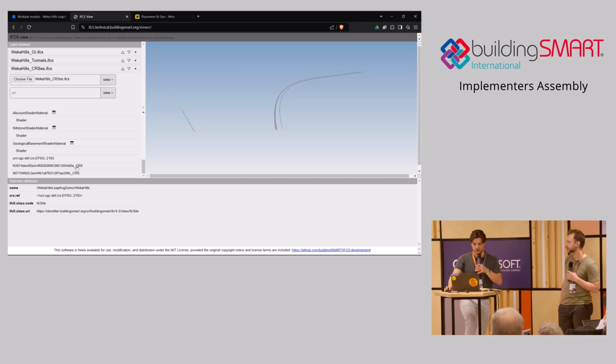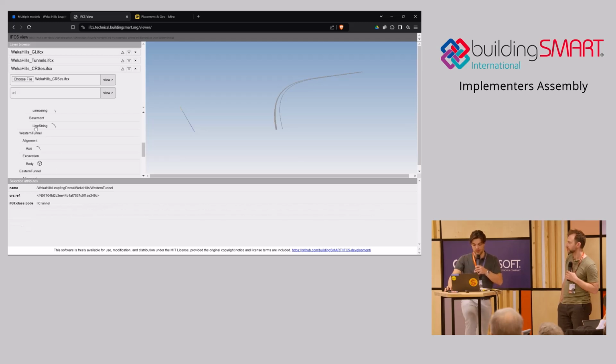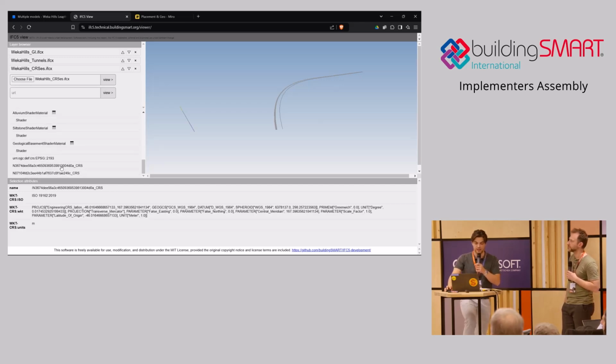Then you can assign those to other hierarchies. For example, maybe you have a tunnel entrance, a BIM model of the tunnel entrance, modeled in Revit or whatever. You export it, and the geometry has some coordinates, 0, 0, somewhere in the middle left corner. Then you georeference it by creating a CRS for that thing specifically, and you create a WKT string for that georeferenced coordinate reference system.